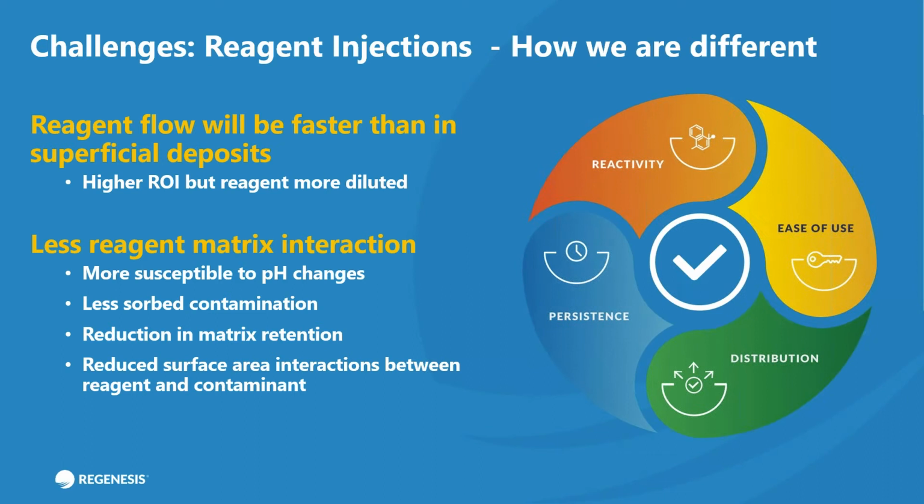But what I would say is the choice of substrate is going to be really important. If you are a remediation contractor, or if you are an environmental consultant and you're auditing, if you like, the different options you have out there, I would argue that these are the 4 key things you need to look at. So the first is distribution, and it's obvious why that's important. If you're injecting something into the subsurface, you want it to distribute far, but not too far, because that will reduce the number of injection wells you're going to need to install into this hard rock.